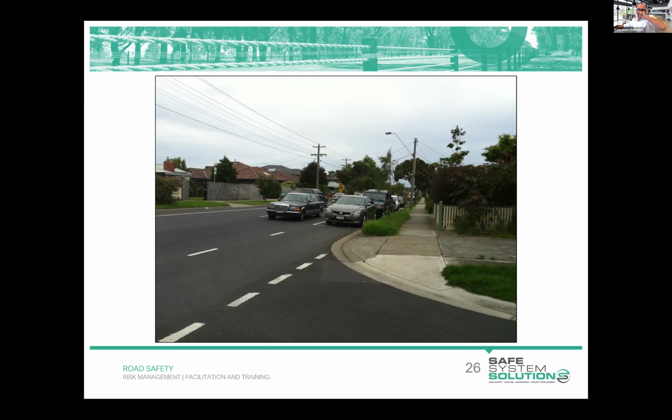Speed reductions on the main road. A bit more support for curb build outs, curb extensions. Possibility of a roundabout. Possibility of traffic calming devices. Gee, it's a good indication that there's a lot of ways you can look to lessen risk, isn't there? That's right. We've got the full suite of treatments there, right from your safe system primary treatments down to the low cost options. So, if you were writing an audit finding, I would suggest that you include quite a number of those in your recommendations.